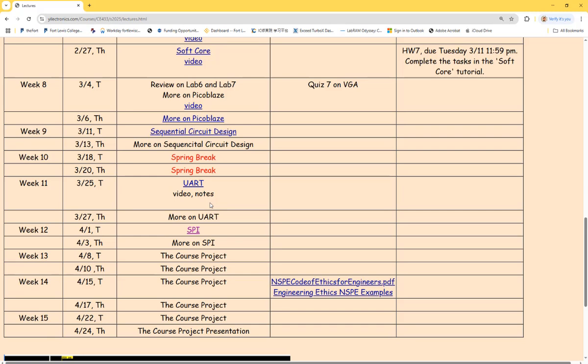And a lot of times UART is being used for wireless communications. So any wireless modules like Wi-Fi or Bluetooth, you can find they have RX and TX on them. It's probably because it's very slow, so it's a little bit more resilient to high frequency RF signals. Maybe, I don't know. And for SPI, usually you can find SPI on SD cards.